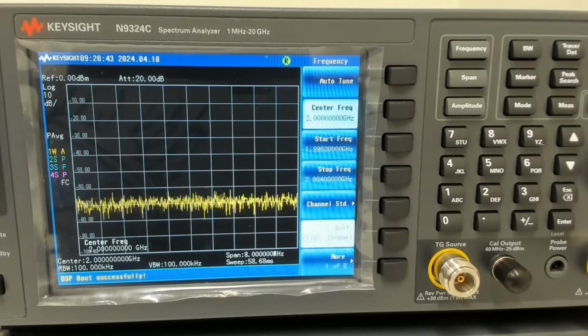In this video, I'm going to show you how to connect a basic spectrum analyzer to the Ethernet port so that you can have a remote desktop. It means that you can control this basic spectrum analyzer from the comfort of your office and run it through your computer. So it's a bit different from the rest of the X series spectrum analyzers from Keysight. The rest of them you can actually use VNC for that purpose, but not for this basic spectrum analyzer.